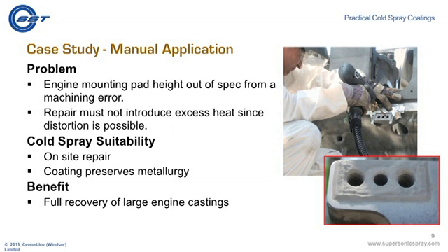This is an example of an SST field service where we actually put one of our SST technicians at the customer site. So it was an on-site repair. The application went very well. You can see the three-hole engine mount there has a fair amount of nickel coating applied to it. The customer would just put this back through his normal operations and finish it to his correct tolerance.